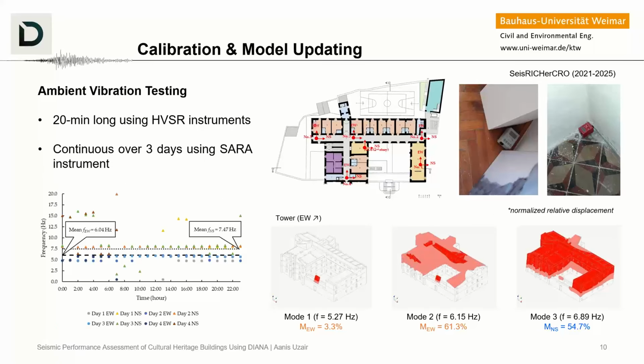Now, in this case, we went to the site and we monitored the building response in 2 orthogonal directions using the instruments that look like this. Now, we took many sets of measurements, and they are all ambient vibration testing instruments. So we took many sets of measurements at these locations. Each of the sets was about 20 minutes long.